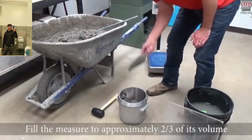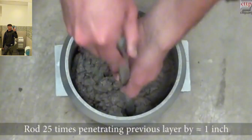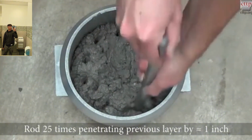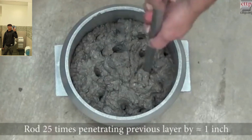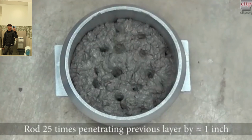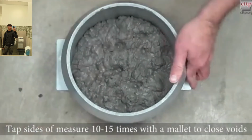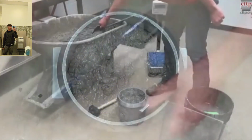Fill the measure to approximately 2/3 of its volume. Rod 25 times, penetrating the previous layer by 1 inch. Tap the sides of the measure 10 to 15 times with the mallet to close voids.